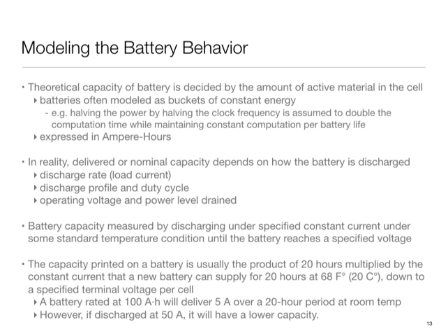So that's what it is rated as. The rated current is 5 amps. Essentially, you take this number and divide it by 20 hours; that's the current which was being used for defining it. If you use a different current, then the product will not remain the same, because this number will change. If discharged at 50 amps, it will actually have a lower capacity, and if you discharge it at 1 amp, it will have a higher capacity.